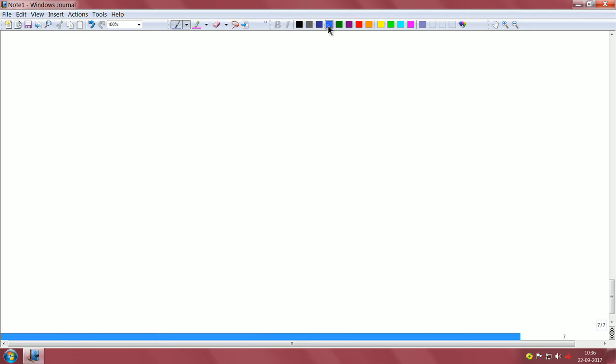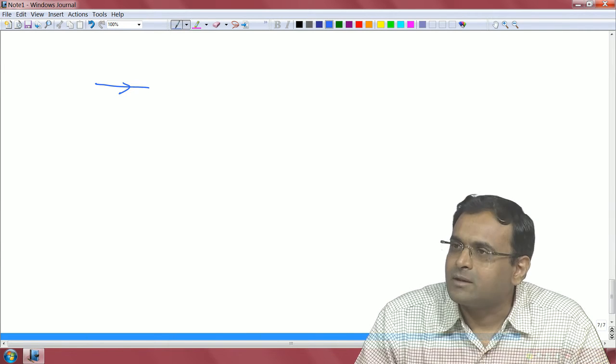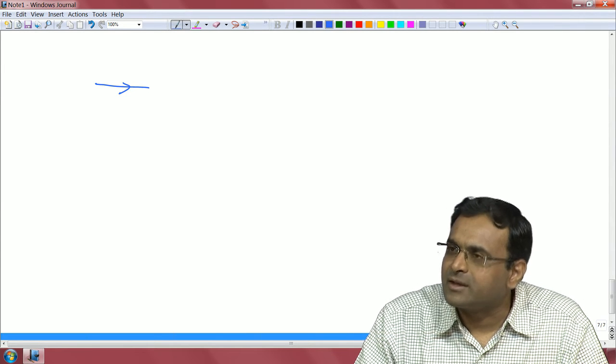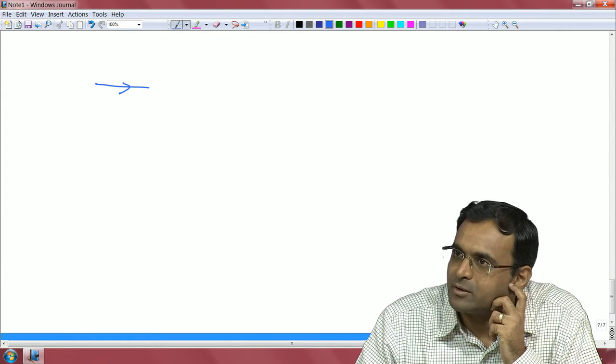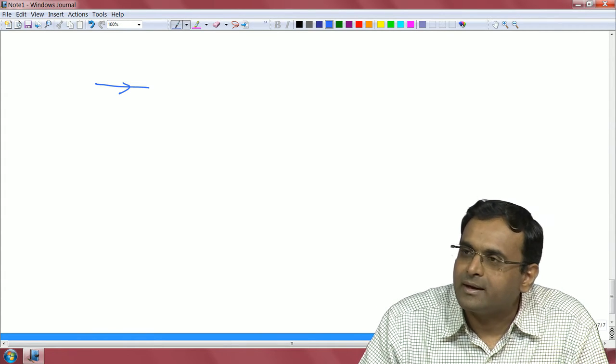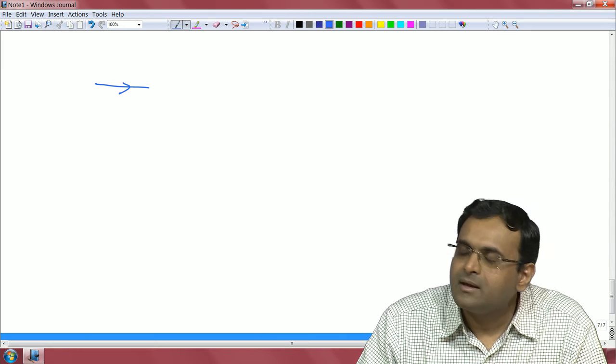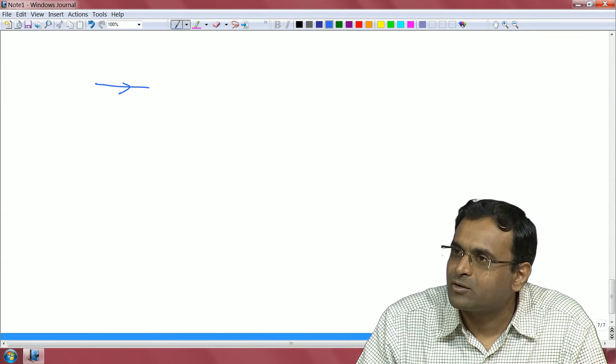Now, from the intuition we have from architecture 3, right. So, architecture 2 is still no good because you have the base filter which is 5000 length long, and if you just filter with that, you are still going to burn that much amount of power because you are filtering through a filter of huge filter order, right.